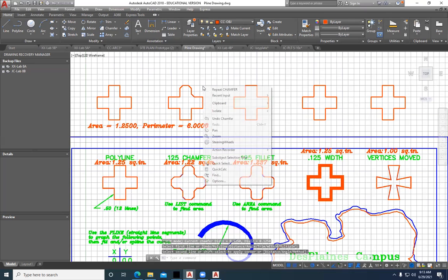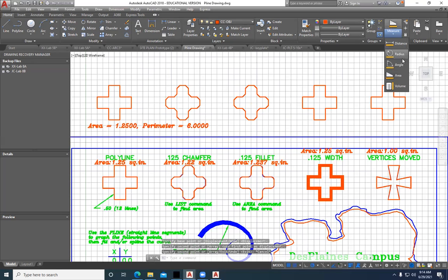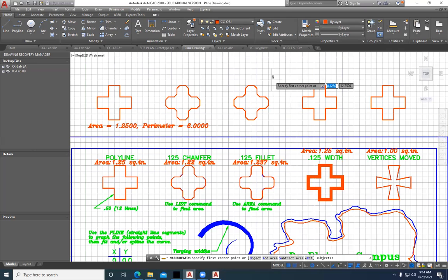And so you'll chamfer this. So if I go to repeat chamfer command, and then I say polyline, I'll do this one because I don't want to double chamfer the corners. It will then chamfer those edges. I can delete this one, copy this one. When you copy something, you select it, then you hit enter, then you give it the base point and the destination point. And then you can calculate out the mass properties like area, down arrow, object, select the object, hit enter, and then it will calculate out that area for you.